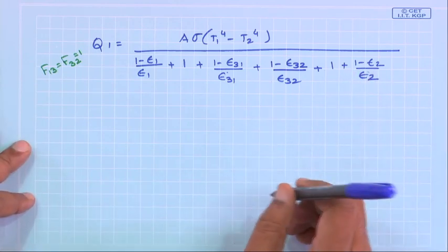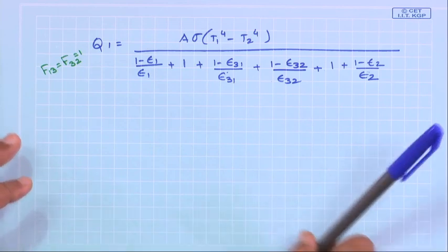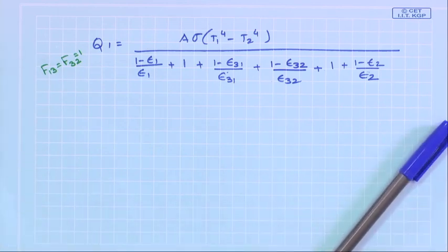So, your aim through the use of this shield is to reduce the amount of heat that one is going to lose or gain, depending on what application you have in mind. So, when you are choosing the material of construction for the radiation shield, the only value that you have to consider is the emissivity. If you look at the expression once again, you would be able to tell what is the property that you want.